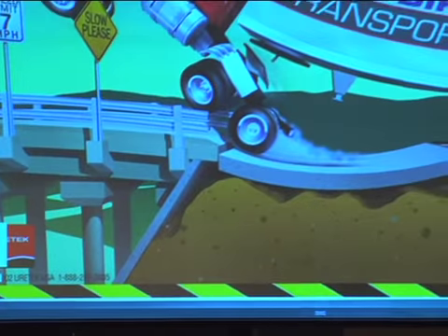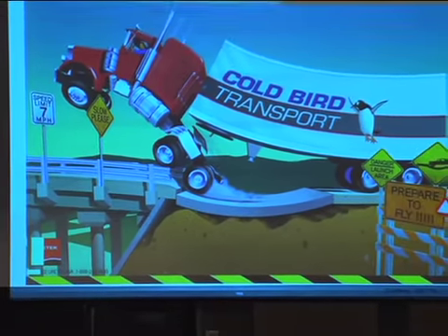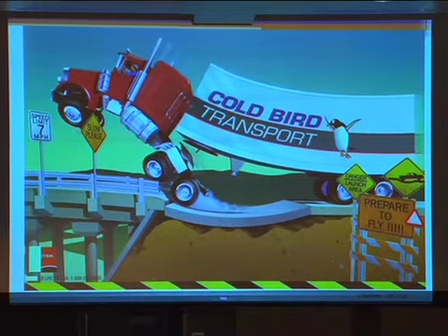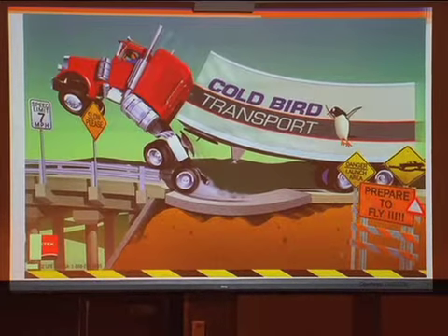Now this is a little bit of an exaggeration, but nevertheless, you do have bridge approach slab settlement, a huge amount of problem in the state. We have several bridges here that have embankment heights anywhere from 15 to 30 plus feet. This particular one that I'm going to present has 40 feet. So where do the settlements of these bridge approach slabs come from?